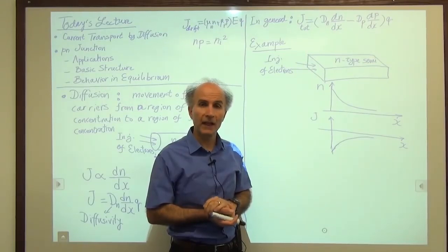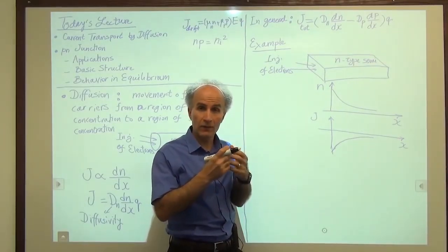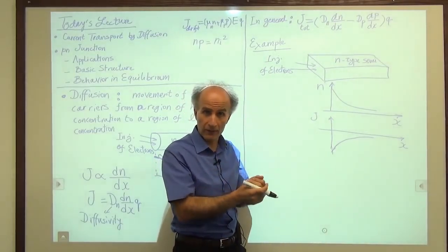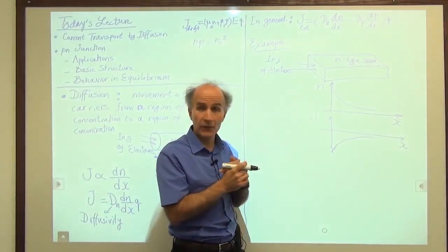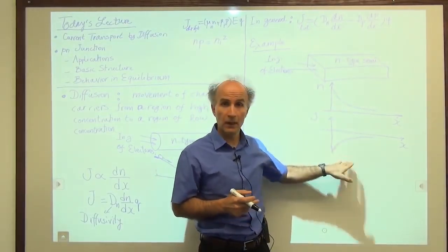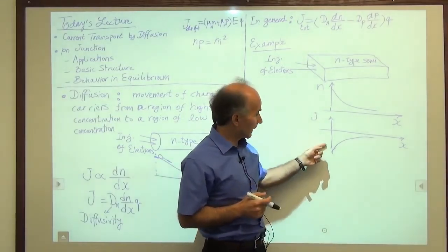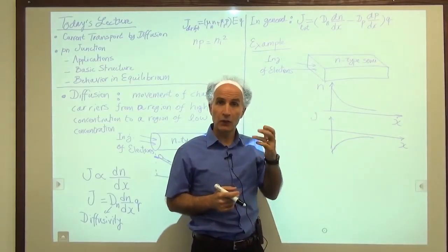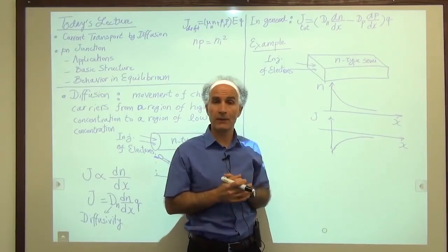Why is the amount of current less? Are the electrons just disappearing in thin air, or is something happening to the electrons? Well, if indeed we observe this behavior, it only means one thing. It means that the electrons propagating in the positive x direction must be recombining with the holes that are present in that piece of semiconductor.